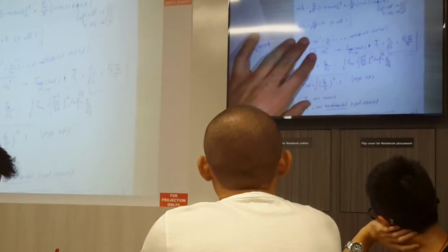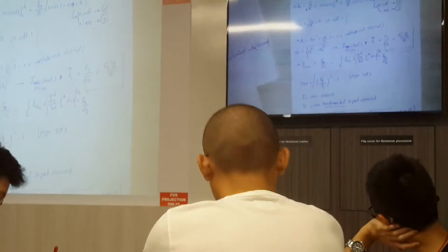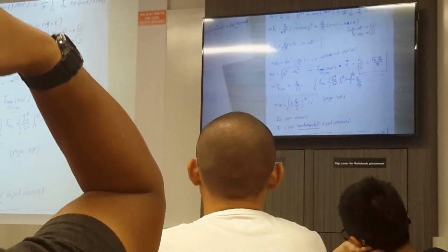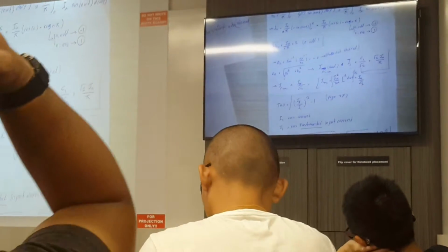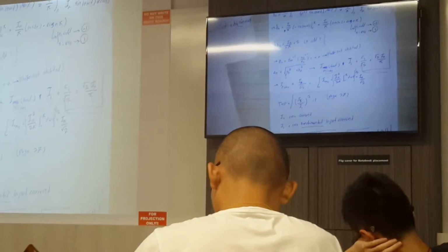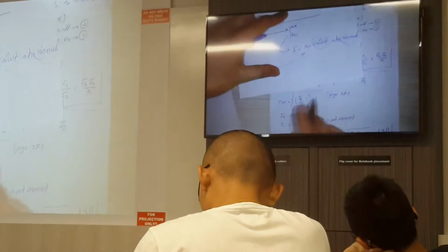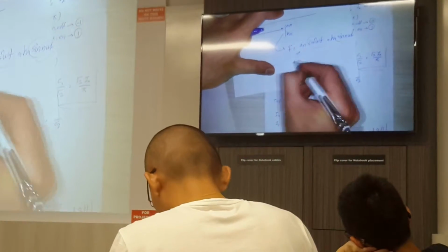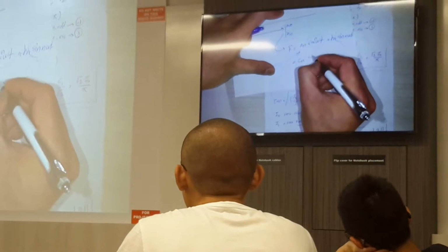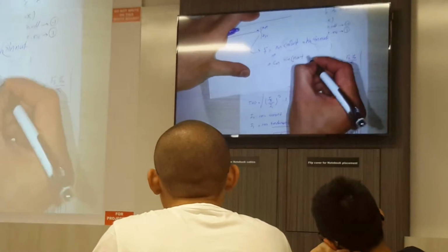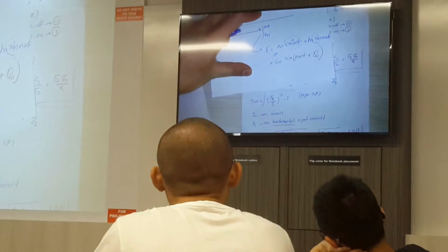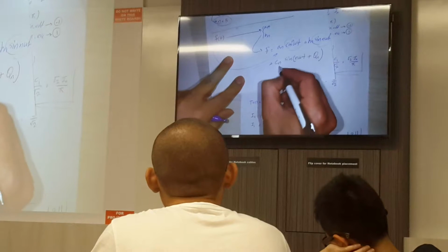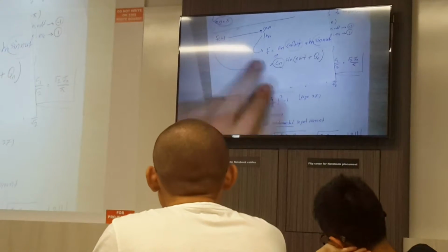So here we have calculated Bn, which is in our Fourier transform. Now for the Fourier transform, we can also write, instead of writing an cosine n omega t plus Bn sine n omega t, this whole thing as Cn sine n omega t plus phi n. So this Cn is the whole amplitude of our signal for the nth harmonic.